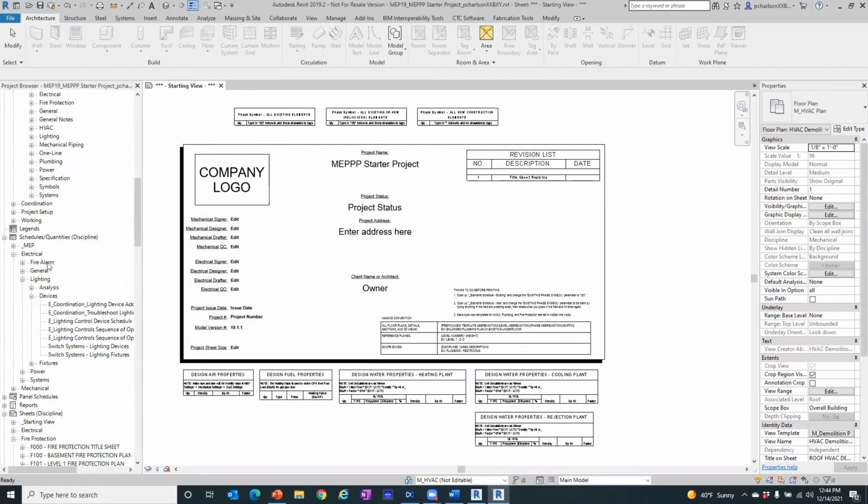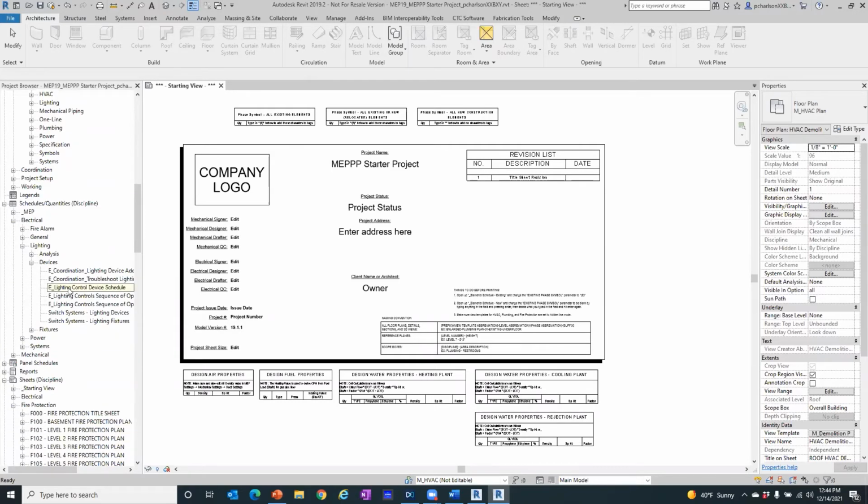If we go to the schedules, this one probably has a few more schedules, but we can also, again, go out to the schedule project and load in the different types that are not currently in the project. You may also want to go in and remove some of those schedules that are in the template for ones that you're never going to use. If you never do fire protection sprinklers, you'd probably go in and remove those types of schedules out of the project. If you need them back in, you can just go out to the schedules project and load them in on an as needed basis.